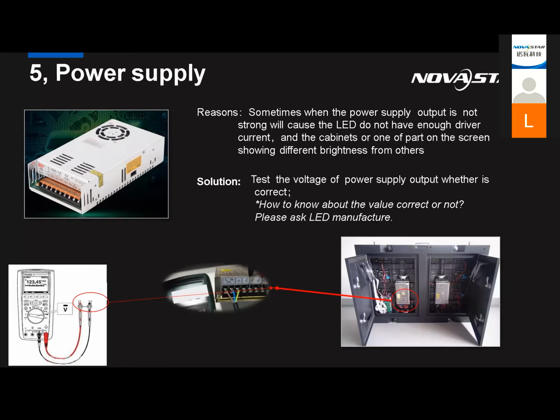So I flew to the city, and when I opened the back door of this cabinet, I saw the power supply doesn't work. So power supply could be a reason for this kind of issue: a black cabinet, a low brightness cabinet.